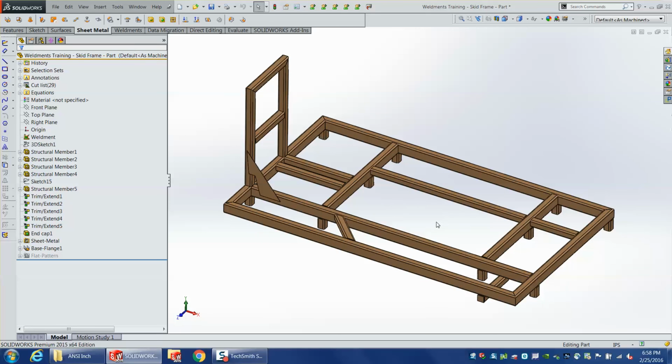Yeah. One nice thing that we do, that we didn't do at first, was basically start weldments. So if you've got a weldment type that you do a lot, maybe like a weldment of a tube with a plate on it, you can actually save those as start files, and start right from there instead of from scratch. All the information is inside of it, so you can make changes, make it bigger, shorter, taller. Kind of a cool thing to do.